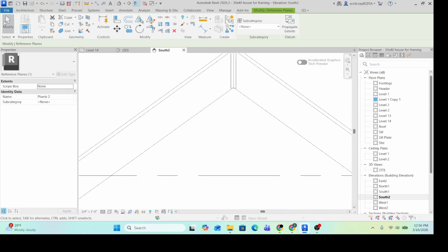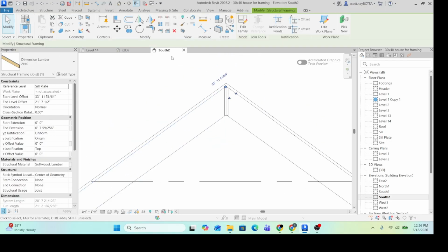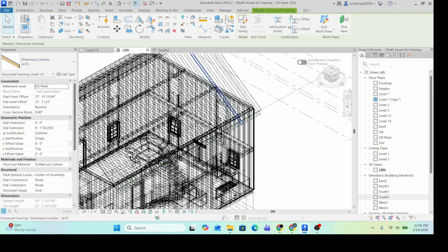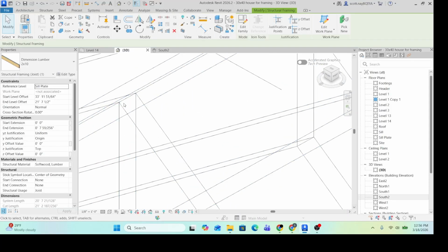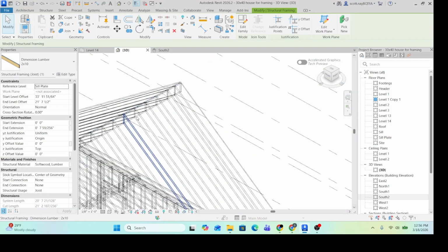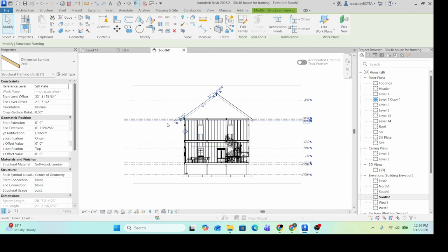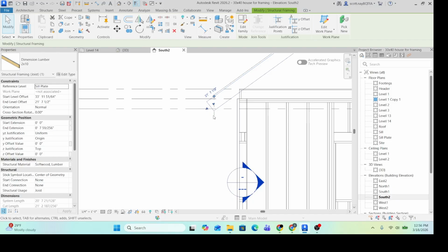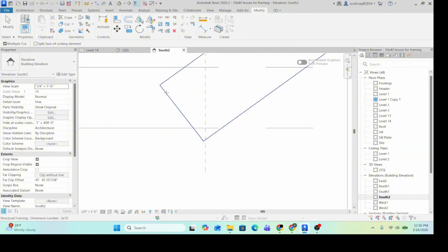I'm going to check the 3D view and see what happened here, because that's interesting that it trimmed them. Oh, yeah. Alright, so we're first going to cut these. I'm going to come into cut. You want to make sure multiple cut is on. You're going to click first your rafter, then your reference plane, and now you're just going to go 30 more times.